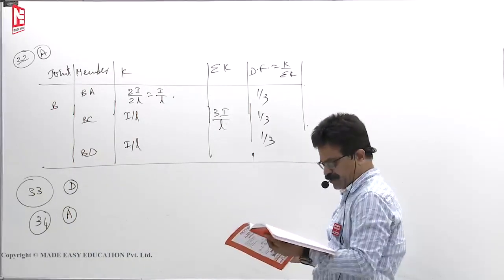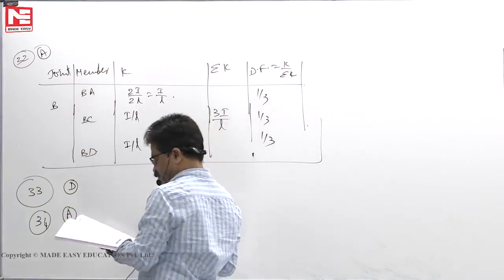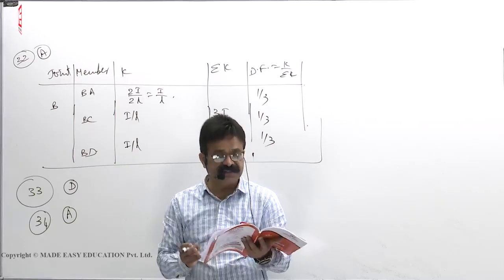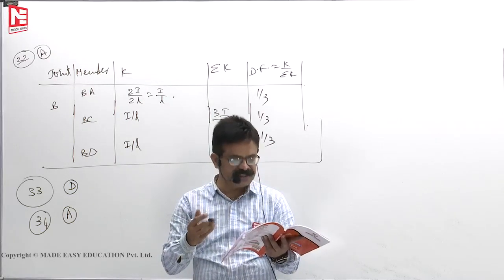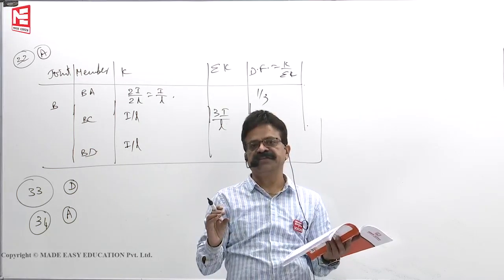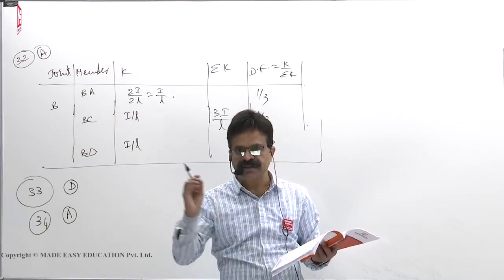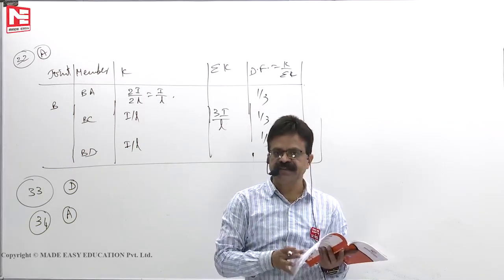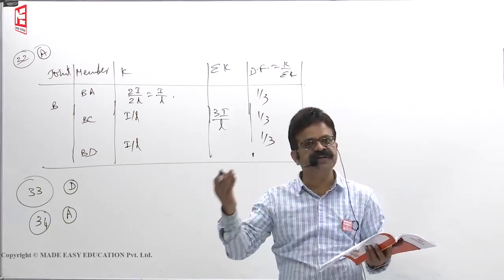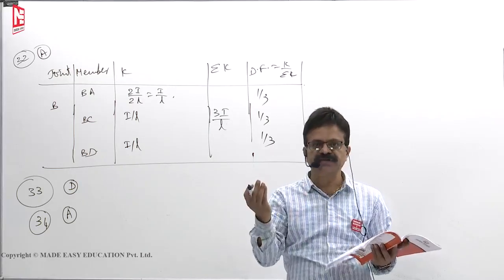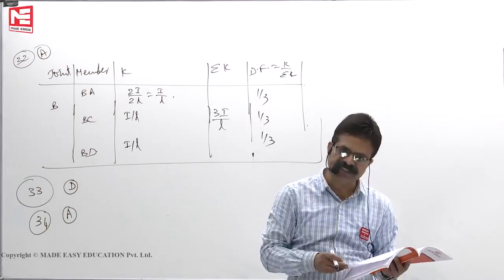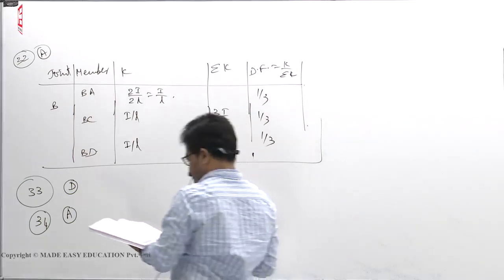Put a minimum of potential energy. Next. Then the minimization of the energy with respect to displacement, we cannot call it the principle of minimum strain energy. Minimum strain energy means energy should be differentiated with respect to force. Then what you get is minimum strain energy. If strain energy is differentiated with respect to displacement, what you get is force. Then dou E by dou delta is equal to 0 will not give you minimization of potential energy or minimization of strain energy. Okay, then 35.